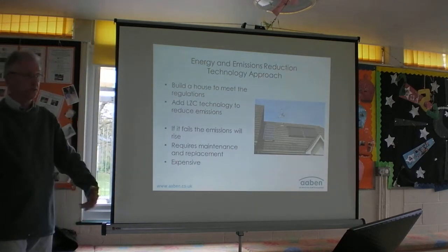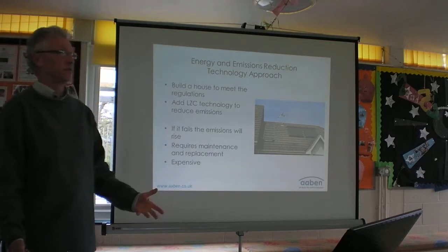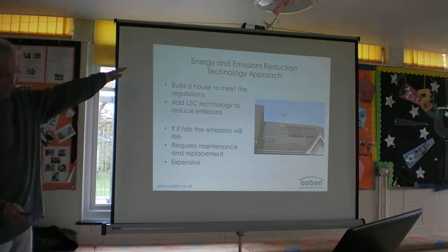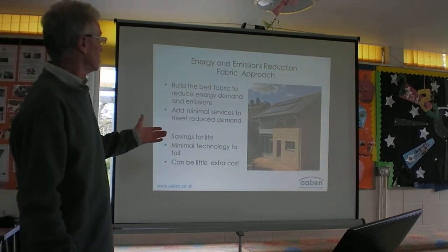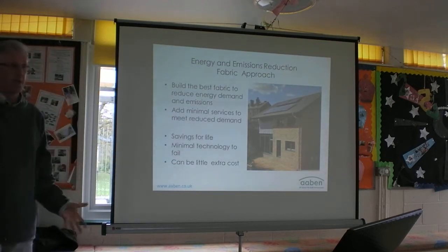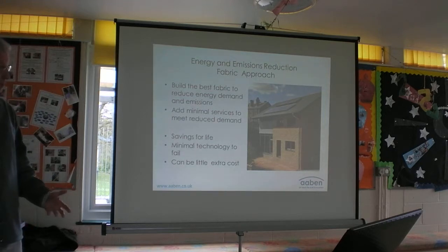It requires maintenance, it requires replacement after 10, 15 or 20 years. Houses last 100 years plus. Okay, that's the technology approach. Or you take the energy and emissions reduction by fabric approach. You build the best possible envelope you can. You spend the money once, you spend a bit more money.